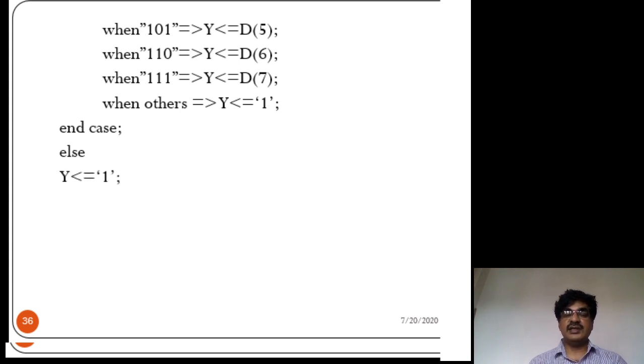Equal to 0 you have to write. Okay, so end if, I am going to end the if condition, and also I am going to end the process. Then before ending the architecture, you know you have another output, that is active low output. So for that I am writing a simple statement: YL <= not Y. Whatever the Y consists within the process is complemented and assigned to the YL. Okay, next end architecture name.